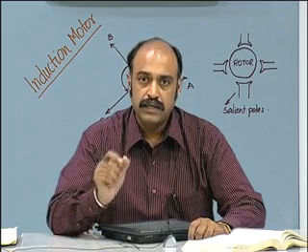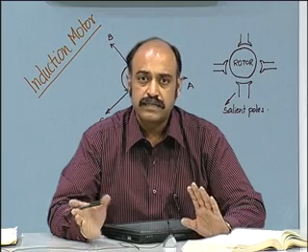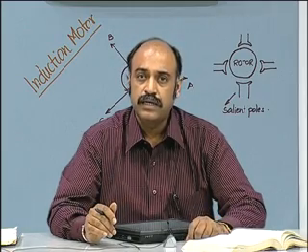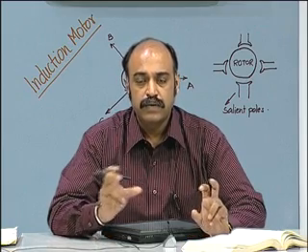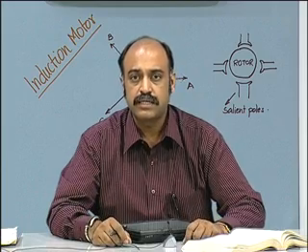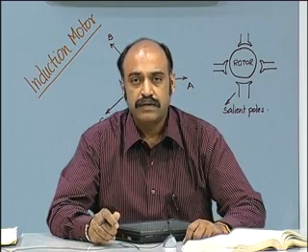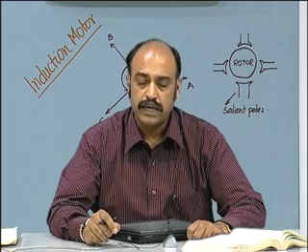And the leakage reactances, when you take it into the equivalent stator side equivalence, they don't have a variation with respect to frequency because the stator frequency is constant. The variation in the speed is taken care of by the R2 by S component.